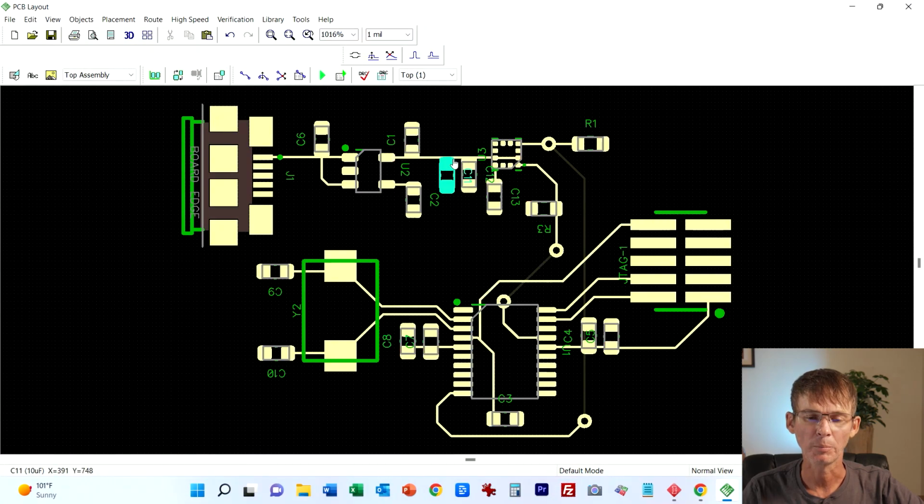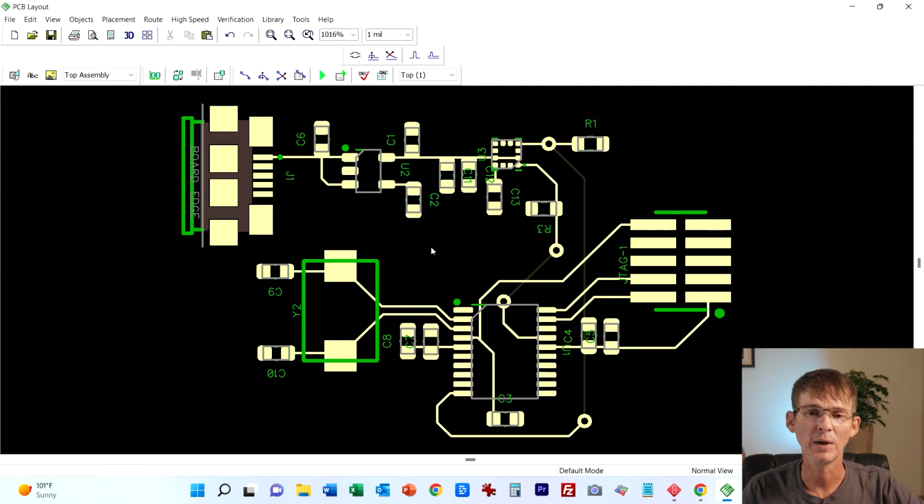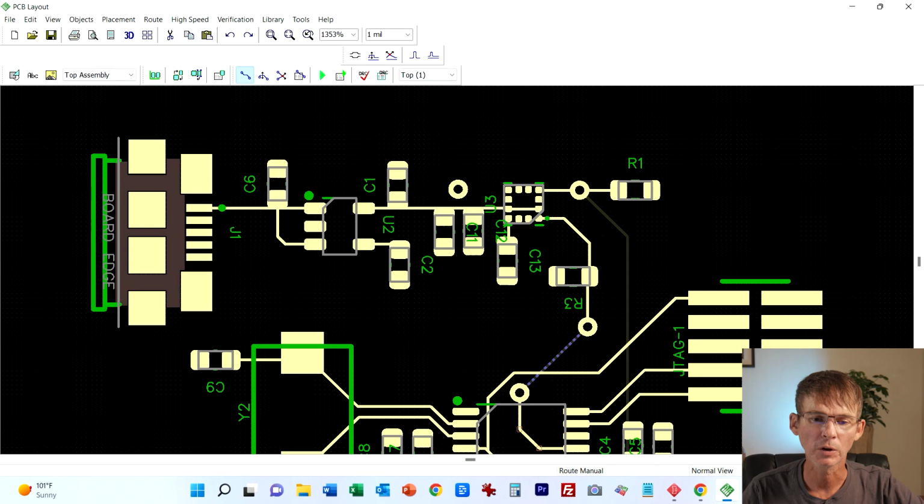into the top. So what we can do here is just do a via, and what I'm going to use it for is to connect up. Well, let's move this over closer to the capacitor, to the actual output of the regulator, and we can just tie that to this supply line.